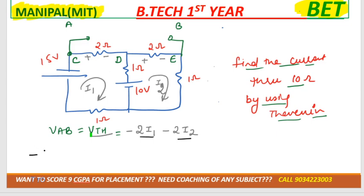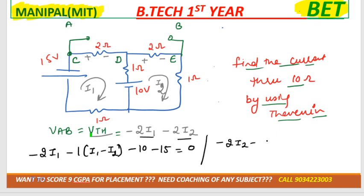For the first mesh, it is minus 2I1 minus 1 into (I1 minus I2) minus 10 minus 15 equal to 0, right? For the second mesh, it would be minus 2I2 minus 1I2 plus 10 minus 1 into (I2 minus I1) equal to 0, correct?